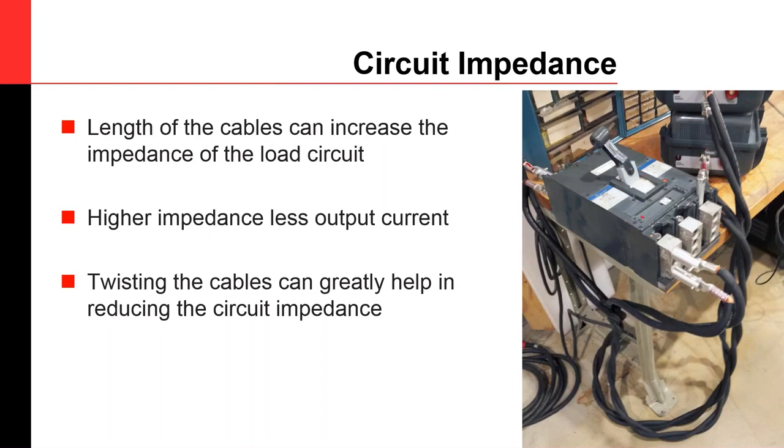That means if you hook up two very different breakers with different lengths for the leads and everything, and you tell the instrument to run 1000 amps, in one case you could measure 2.5 volts at the output, and in the other case 5 volts. The unit will regulate within its capabilities to compensate the burdening that it is exposed to by the test device. So it's a current source.